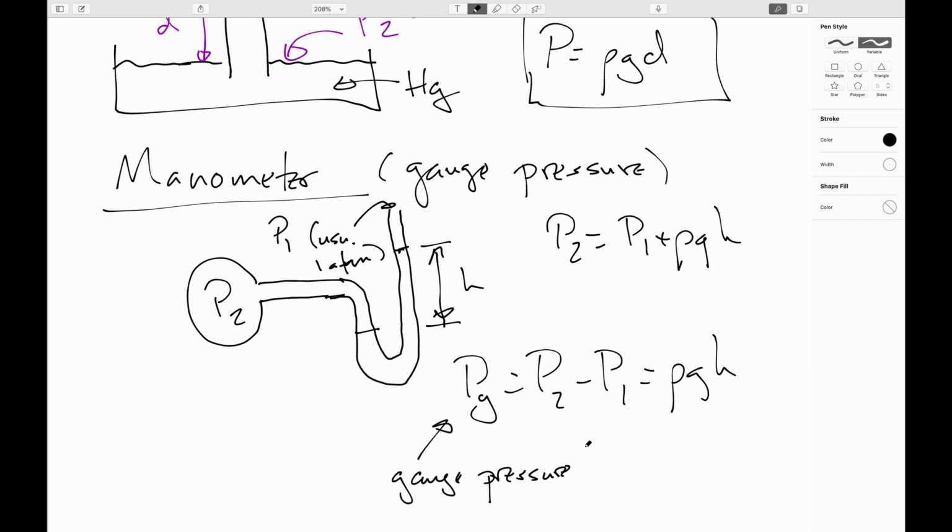Now, an important thing to keep straight here is that absolute pressure can only ever be a positive number, but it is totally possible for gauge pressure to go negative, because it's comparing the pressure between, say, the inside of something and the outside of something. So in this case, you may be aware of what are called negative pressure buildings or negative pressure rooms. I used to work in a negative pressure building once a long time ago.